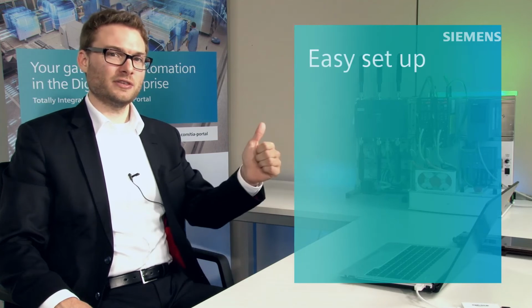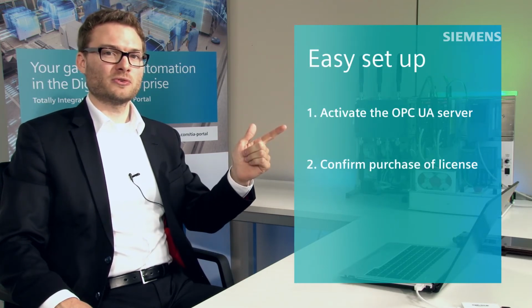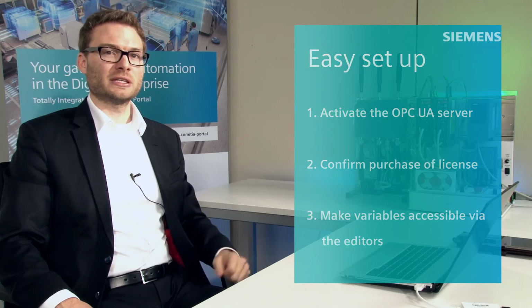It just takes 3 simple steps to configure OPC UA in the TIA portal. Activate the OPC UA server, confirm the purchase of the corresponding runtime option, then mark individual variables accessible through OPC UA directly in the editors. And now I'm going to show you everything in practice.